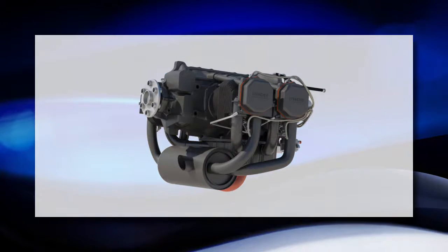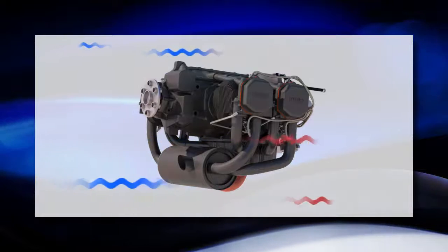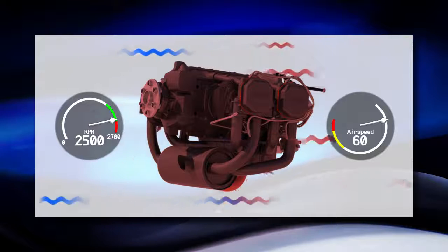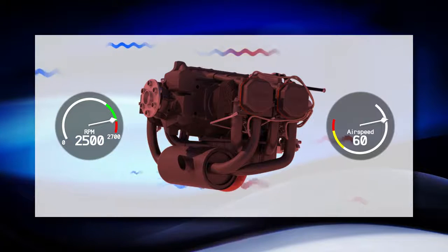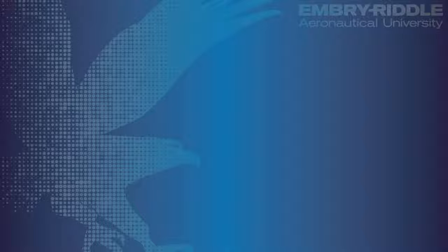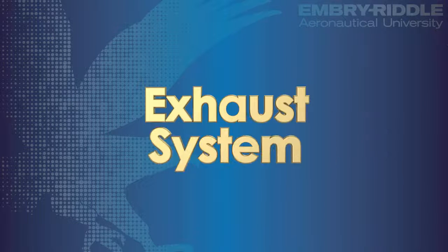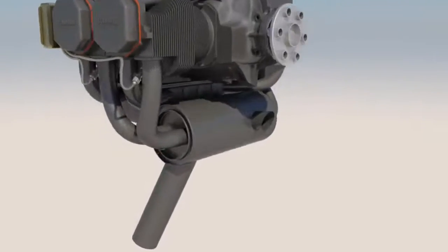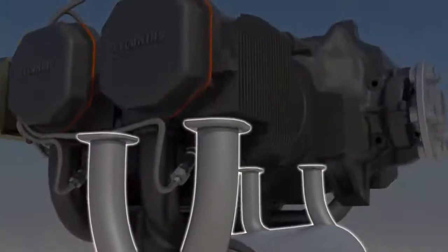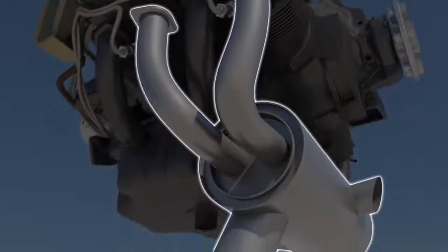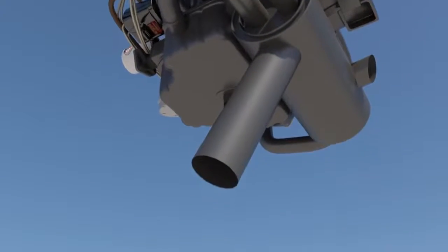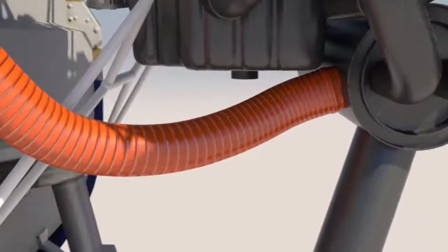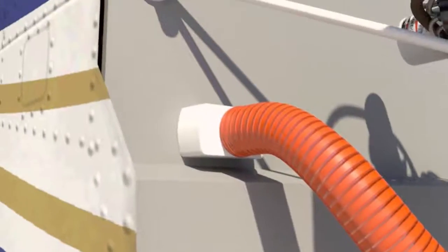This method of cooling can be severely restricted, however. When the airplane is running at high power and at very low speed, such as when climbing, airflow is minimized, causing higher temperatures. The last step in the four-stroke cycle is the exhaust. The exhaust system has a dual purpose in most general aviation airplanes. As expected, the exhaust system does allow the hot exhaust gases in the cylinder to escape the engine in a quiet manner. Additionally, as we'll talk about later, the exhaust system also provides heat to the cabin.